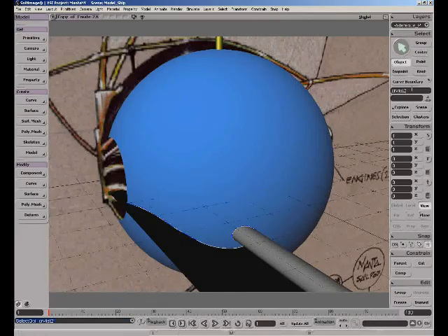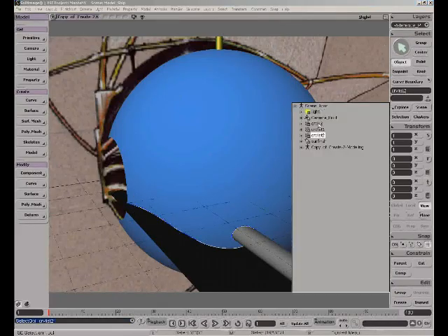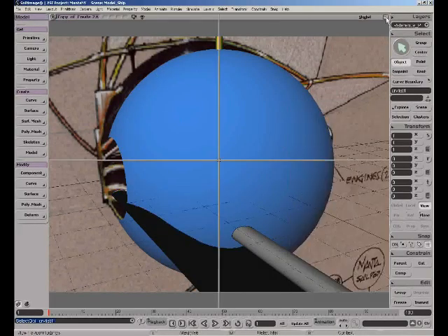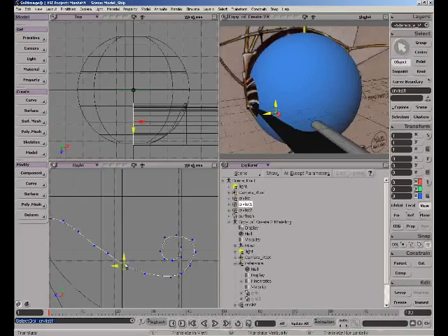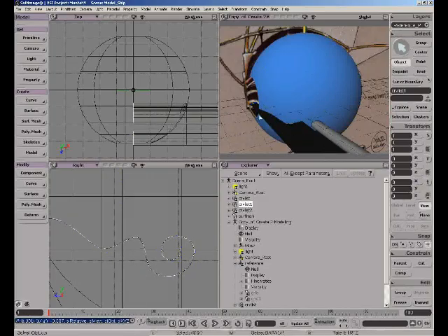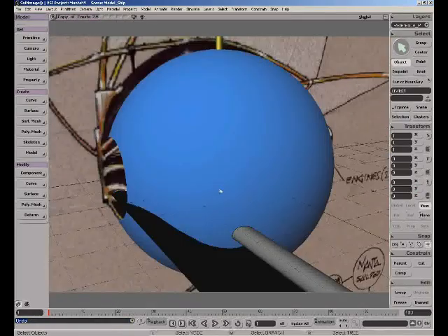And I just want to show you a neat thing about the architecture of XSI. If we go and select the curve that we just drew along the surface of this texture, that reference plate, we can go ahead and move a point, or any point. And notice that everything updates. The extrusion that we pulled out from this curve changes. Also the curve that's actually on the surface of that sphere changes. And this is called relational modeling. Basically everything inside of XSI will follow relational modeling.